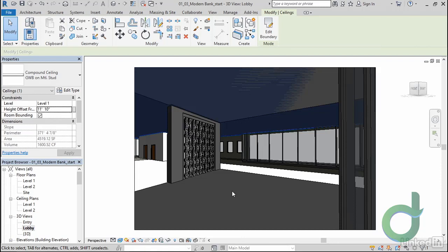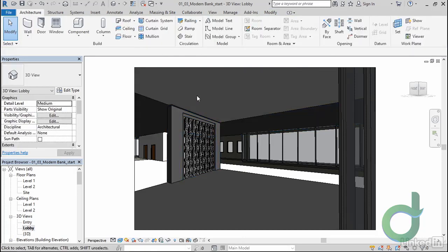Again, would I sometimes put in one whole ceiling here for design in Revit just to see how it flows? Yes. And then I might come in and either edit the boundary or delete and remake prior to putting in can lights, just to make sure that everything joined cleanly and round shapes, such as punch cans, had the opportunity to go in a smaller piece of ceiling instead of the whole thing.